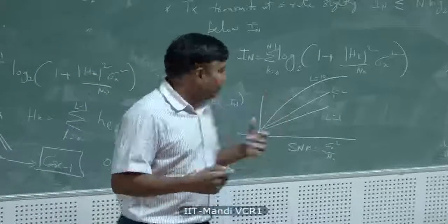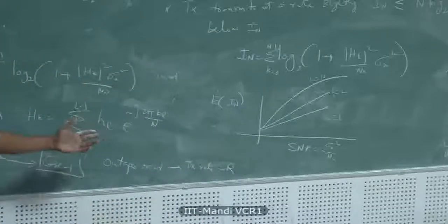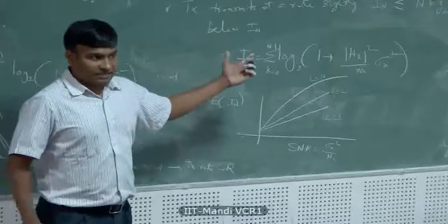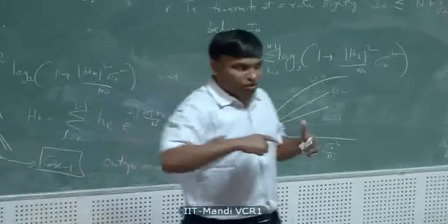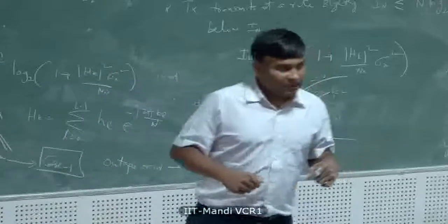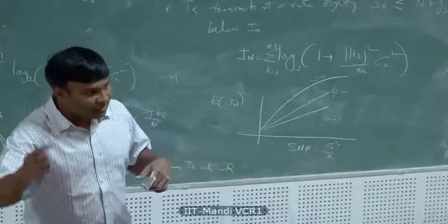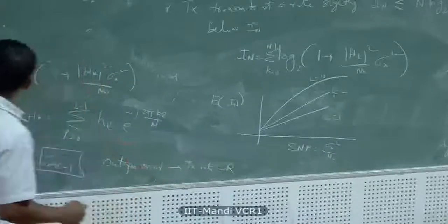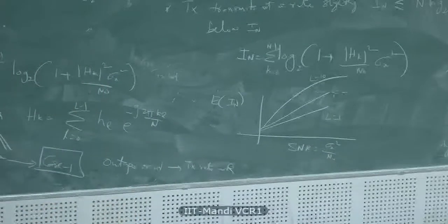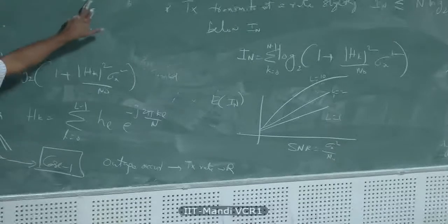The feedback is in the form of either mutual information or some effective SNR. Mutual information has a one-to-one mapping to some effective SNR, and based on that you can control the modulation size and the code rate to come up with a single rate R, which is a product of code rate and log base 2 of the modulation size.